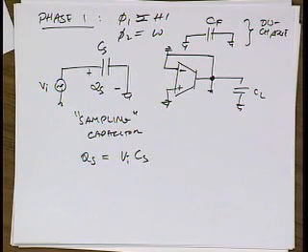In fact, if you go into the lab, I'll give you 5 capacitors, and I'll tell you, go in the lab and discharge them. Okay? What voltage are you going to end up with? You're not going to end up with 0, right? It's going to be some distribution. What's the variance of the voltage you end up with? Anybody? Yes. It should be a function of the parasitic capacitances through which you discharge the capacitor.